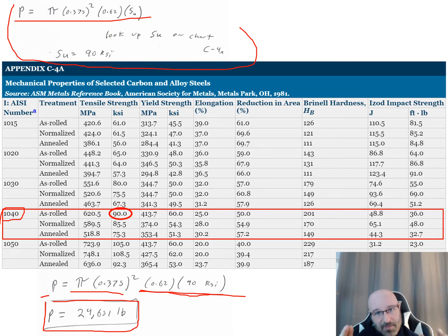Again, thing to think about with this here, because we're talking about the design process as a whole, is your safety factors. So even if you're like, wow, this is like 3 times as much as I'm ever going to experience, well, maybe you want that in there because you're doing this event. Look at your assumptions. A static loading. What if it was a dynamic impact loading? Is your product, is your part going to hold up to that? So pay attention to all that.